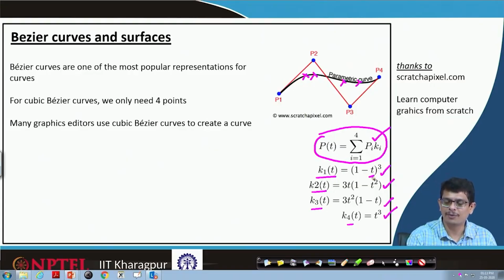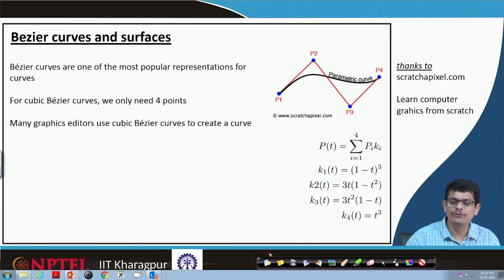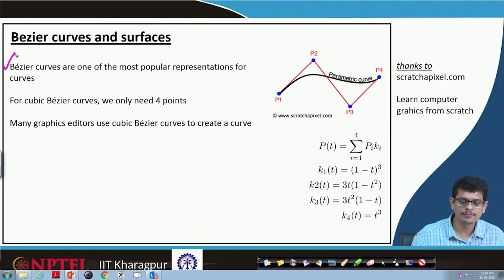So, T is our parametric variable like our U, a cubic polynomial, a cubic, a cubic, in different kinds of formats. We are going to carefully adjust so that we will be in a position to construct polygons through which this particular polynomial curve really passes. If we do that, that kind of curves we call Bezier curves, and these are the most popular representation curves.